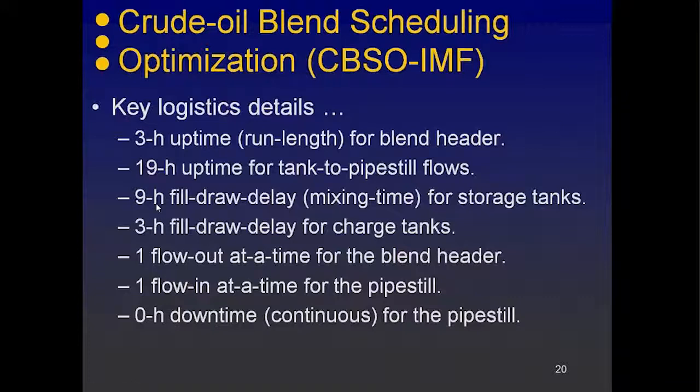You see that a lot when you have crude oil deliveries from the ocean or from marine deliveries, where there's lots of ballast water. So you need to put the crude oil into the tank, and then you need to let it settle for a certain amount of time. 9 hours is probably a little too short. It's more like 24 hours. And then you would remove the water. Then you could send it to the desalter and the downstream crude unit, and then you'll have no fear of blowing out the trays in a crude unit.